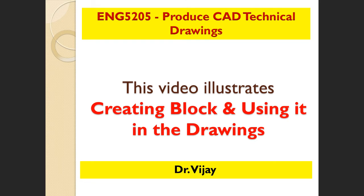A block is nothing but a symbol which we may need to use repeatedly. That's why we create a block and save it in the drawing library, and we can use it multiple times whenever we need. That's the main advantage of using blocks in AutoCAD. I will show you how to create the block and how to insert it in the drawing in this video.